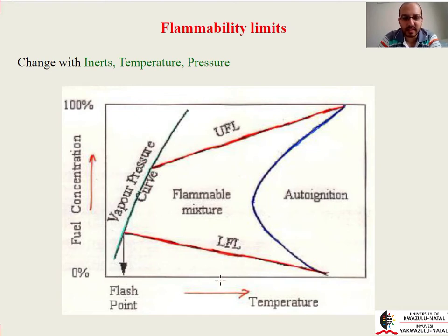As you increase your temperature, the range at which your mixture is flammable increases, because your lower flammability limit decreases and your upper flammability limit increases.